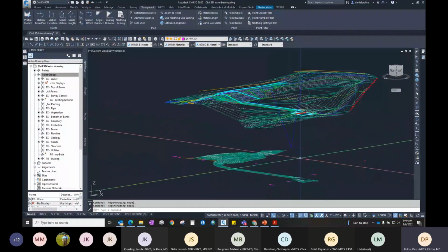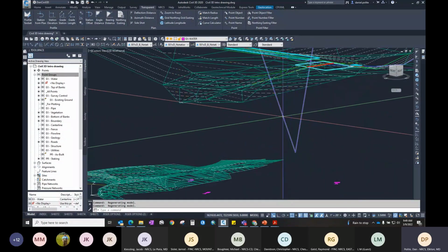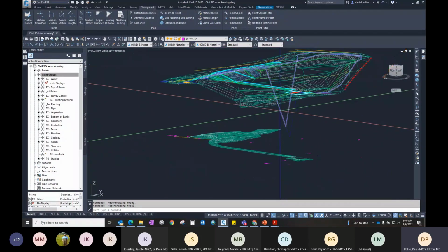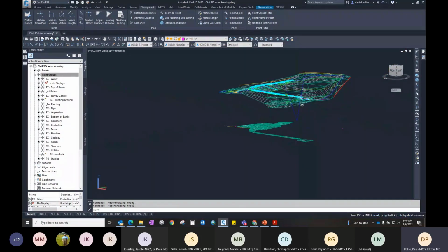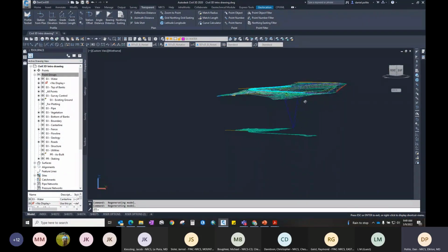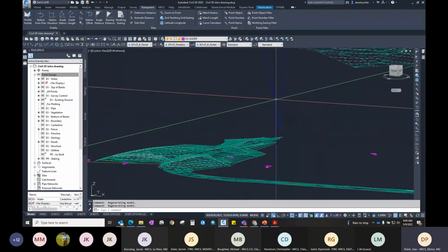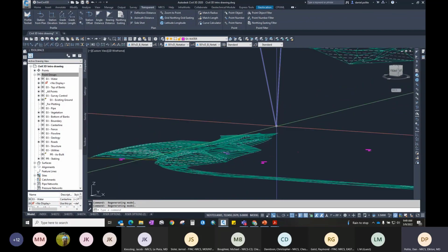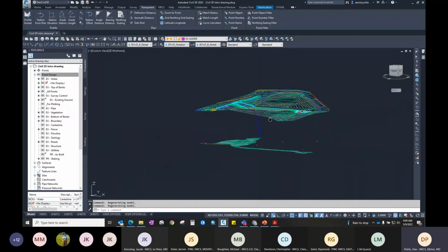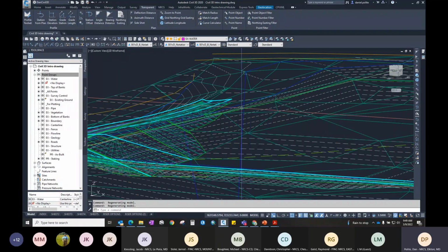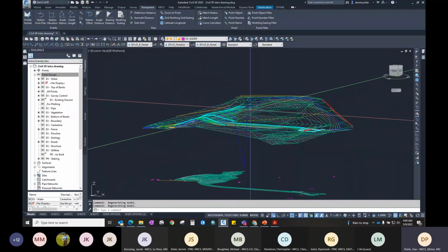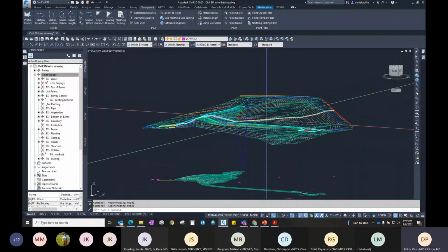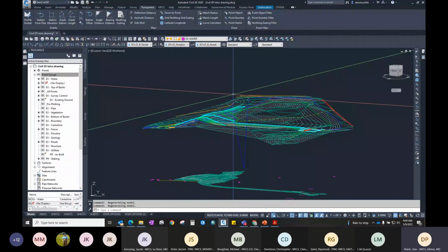And then again, this will tell you what you see that you might have problems with when you are in that Civil 3D location, where this line is probably a break line that was missed, and it's probably sitting on some weird elevation. So it's always a good thing to check that stuff and make sure what you have drawn is correct, I guess.